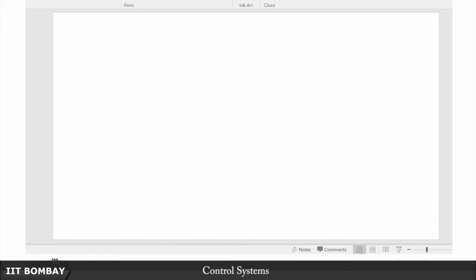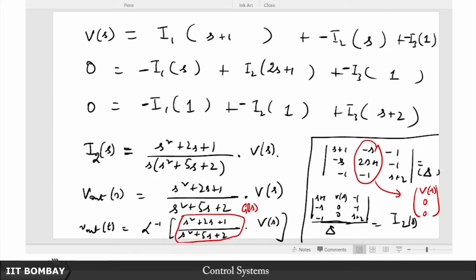Now we've of course used KVL here, Kirchhoff's voltage law, although I told you earlier that if the unknown quantity of your interest is basically a voltage, a node voltage, then you better apply Kirchhoff's current law to simplify the process. And you've already seen here that you determine the current directly, but then you had to multiply it by an S, which is why this S went off, in order to get the voltage. So you had to multiply the current with a suitable impedance in order to get the desired quantity of your interest, which is the voltage.